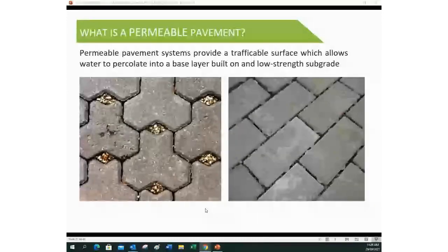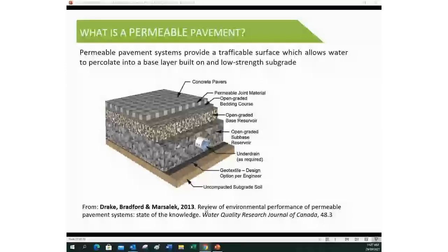And that's what got us looking at permeable paving as a way to work with trees rather than to try and persist on the 10 to 20 year cycle of destruction. You understand what permeable paving is. It lets the water through. It's on a gravel base. A couple of points here. Firstly, a subgrade is an option. Most permeable pavements don't need that.